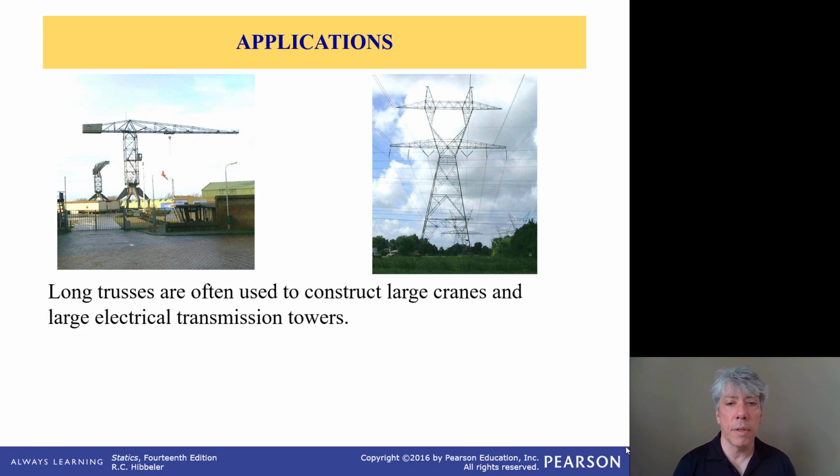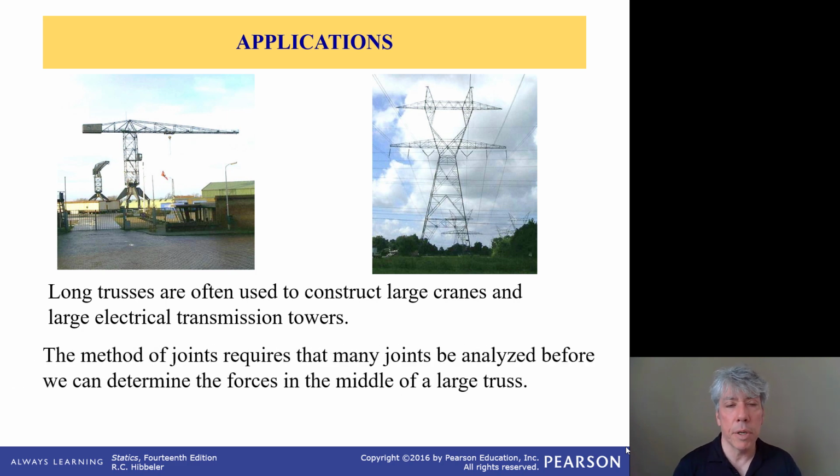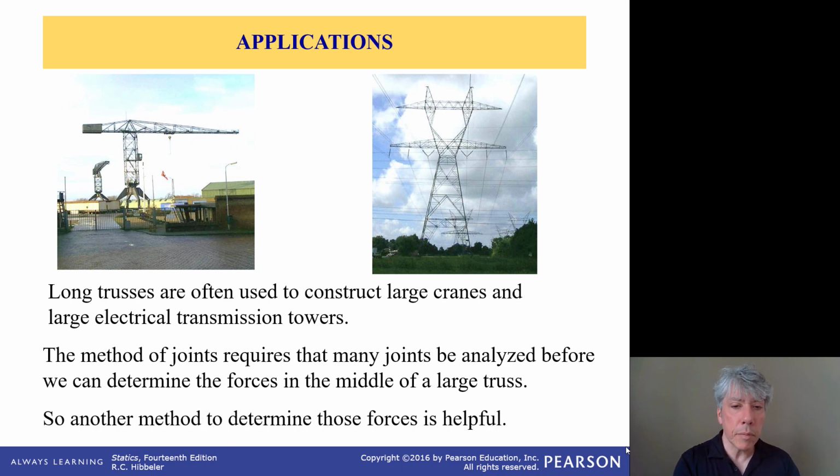And again, often all you really want is the force in particular members, and this method of sections you can think of as a shortcut to get to those loads without having to calculate the load in all the members leading up from the support reactions to the members you're actually interested in. So very often trusses are made with so many members that this method saves you time when all you need is the force in particular members.